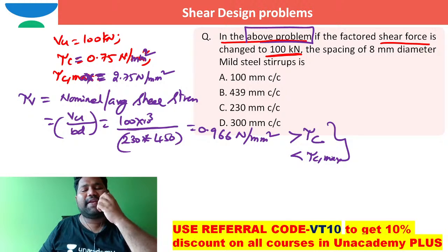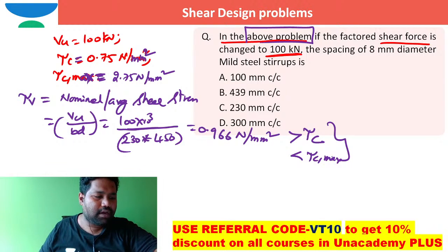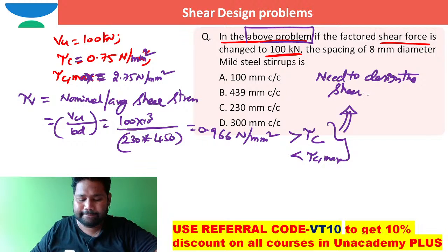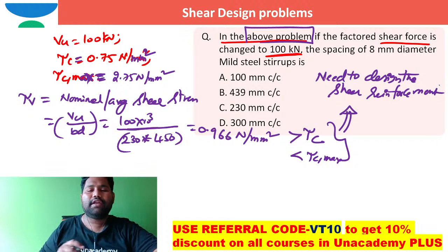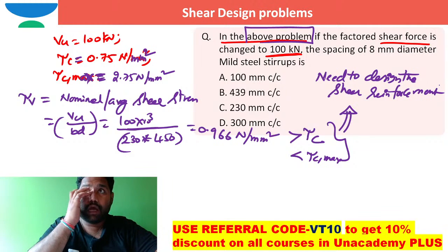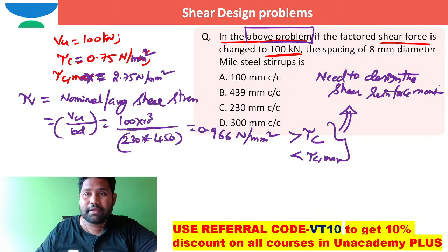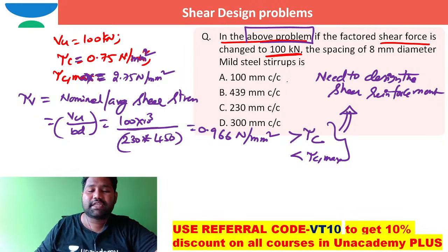So I can say we need to design the shear reinforcement, right? If I need to design the shear reinforcement, how can I design it? By using vertical stirrups, 8 mm diameter mild steel stirrups.